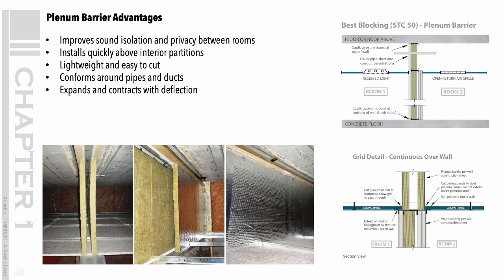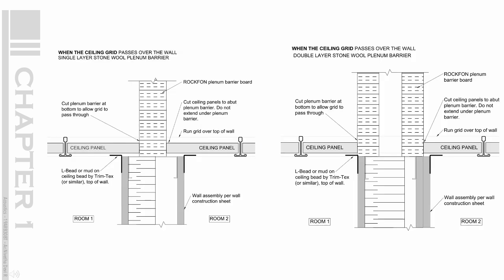Plenum barrier advantages: improved sound isolation and privacy between rooms, installs quickly above interior partitions, lightweight and easy to cut, conforms around pipes and ducts, expands and contracts with deflection. Plenum barrier construction details.